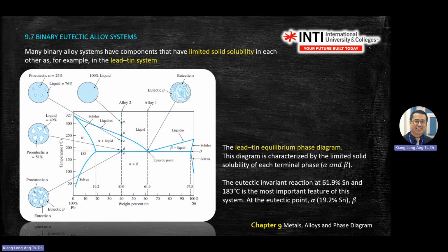So this point forms at one particular temperature. In this case, you follow the line, you draw the straight line, and you will reach one temperature, 183 degrees. This will be very popular in tests. They will ask you to find the eutectic temperature. Usually just use your ruler, find any straight line joining two solids, draw to the left, and you get the temperature.